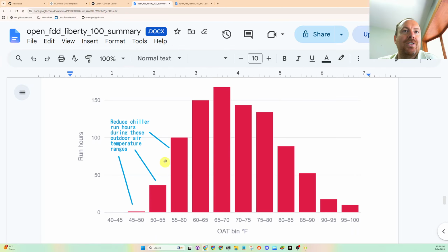That's why they need the chiller operating at these hours, is that these dampers don't work at all. This is my hunch, and that they need the chiller to run even when it's below 55 degrees outside. If that's the case, there could be a reason to get the economizer dampers fully functional. I assume that the building was designed with fully functional economizers.